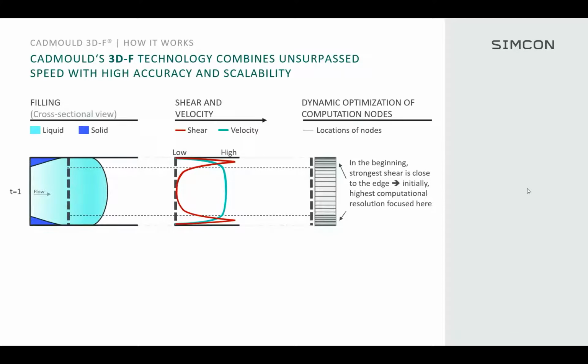Looking at how the plastic flows through the upper and lower walls of the plastic molded part, we can look at the shear forces on the edges are increased, and the speed of the plastic flow in the center is also increased.